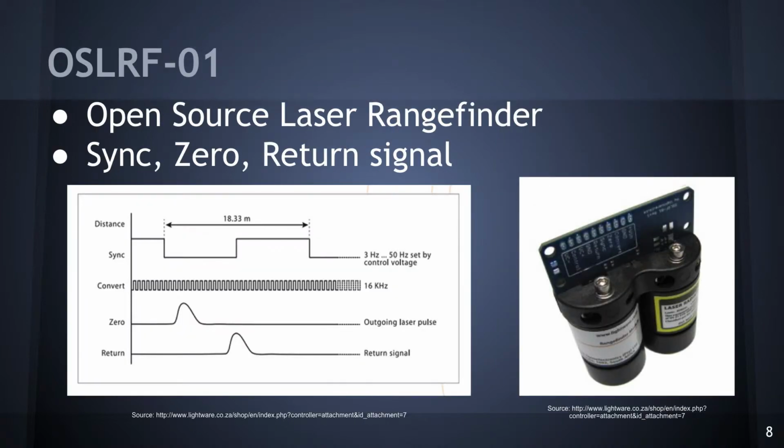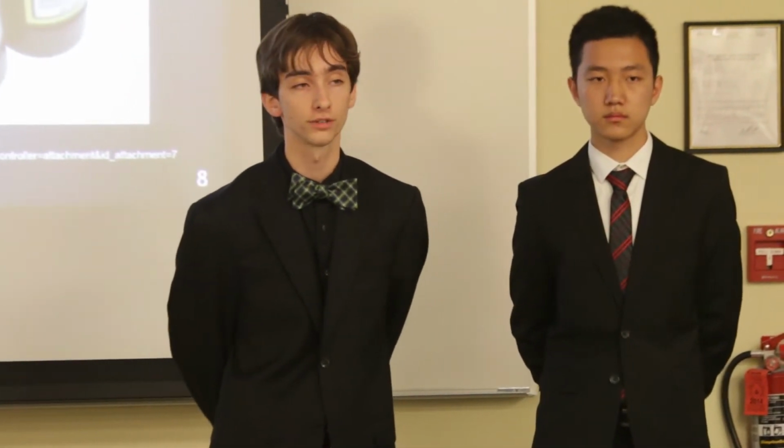The main component of our project was the open source laser rangefinder, which is the first affordable LiDAR sensor available to hobbyists and students. The sensor emits a laser pulse every 122 nanoseconds, which is actually too fast for a microcontroller such as the Arduino to be able to sample to any significant value. For this purpose, there's a circuit within the sensor which expands the timebase.